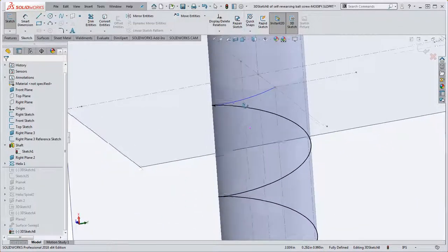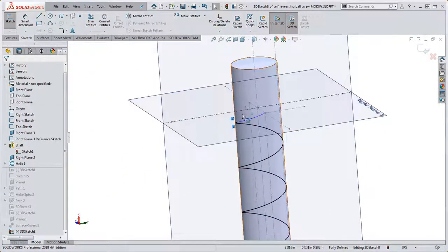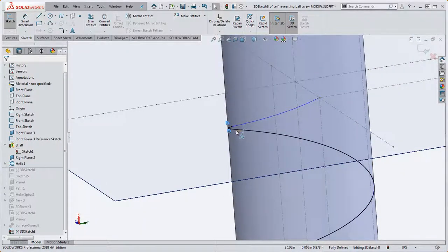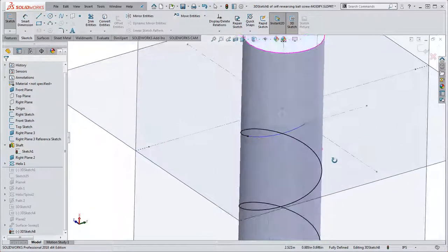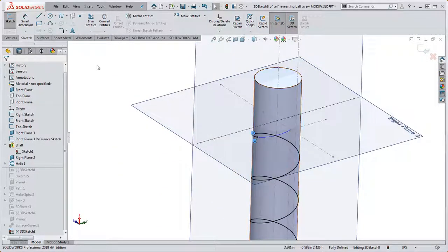So we're kind of truncating this a little bit early. And you can put in other planes in here too and make it terminate in a different way. But the desire here is to put in a curve between that point and this point up here, tangent to the helix on that end, and then tangent to this line on this end. That way it smooths out and comes to a nice transition up here at the very top, and then it can continue back downhill on the other side. That's the desire. So with that in place, we're going to put a curve in here.